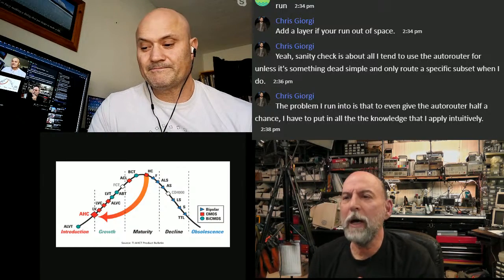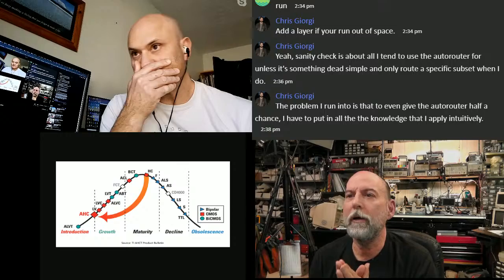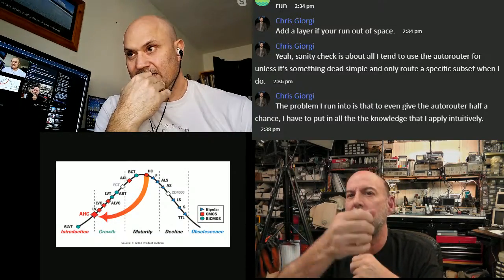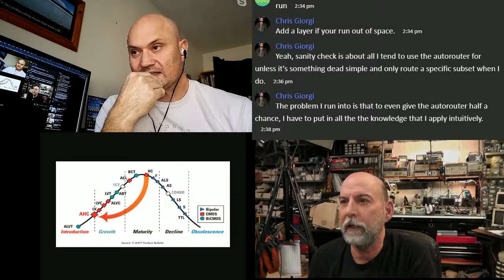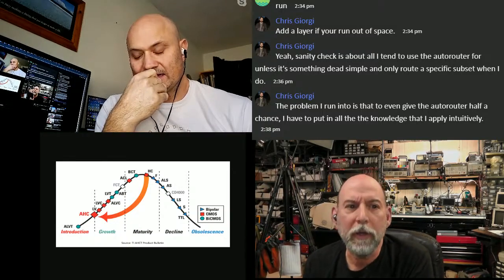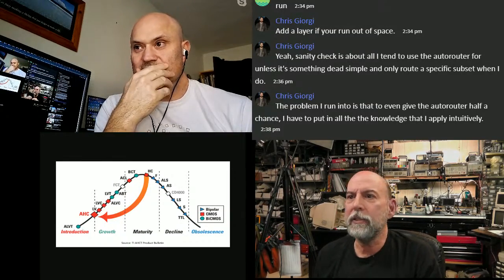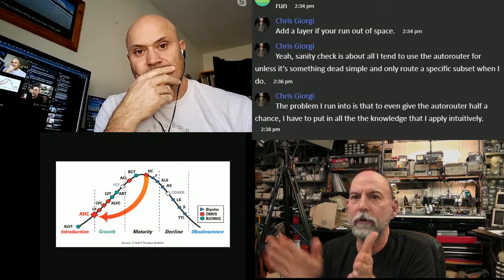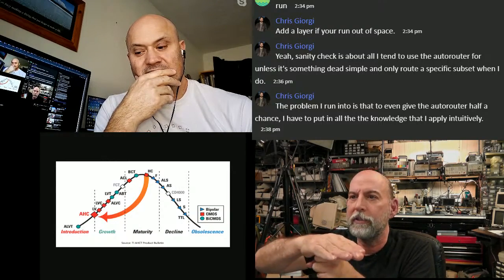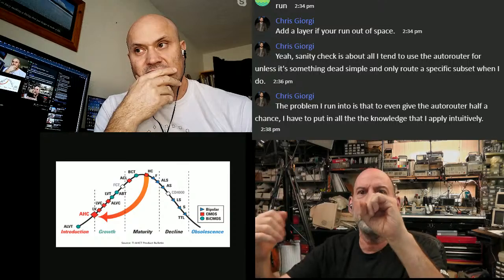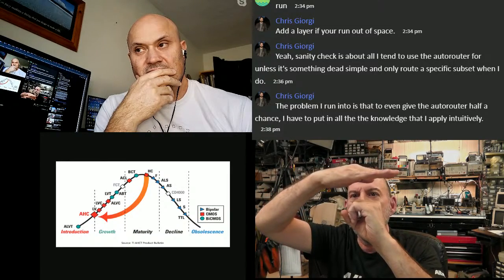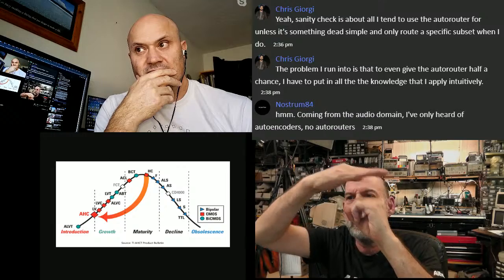Hey, so you know about hug and push, right? On these CAD systems, when we are moving things, it can actually move things that are movable, vias and the like. I have a problem with hug and push though, that it hugs when it doesn't need to. So it'll hug a through hole, for example, like here's the through hole, and then it'll put it here when it had all this room, and when I gloss it, it'll bring it back down close.